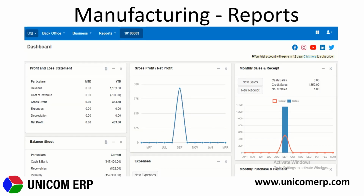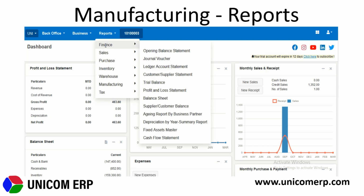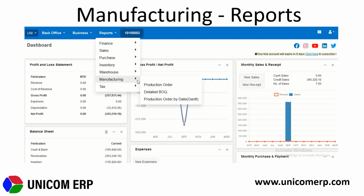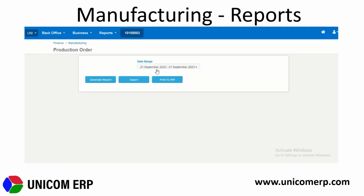Next, we can see the reports associated with manufacturing. To access the reports, navigate to the Report menu and select Manufacturing. There are 3 reports associated with manufacturing: Production Order, Detailed BOQ, and Production Order by Date, which is a chart-based report. Choose the first report option, Production Order. You can select the date range and click on the Generate Report option.